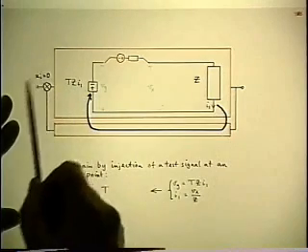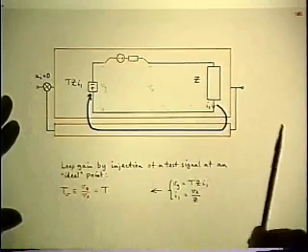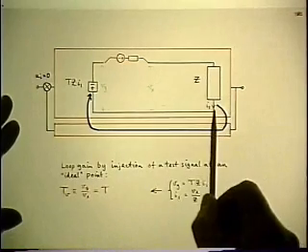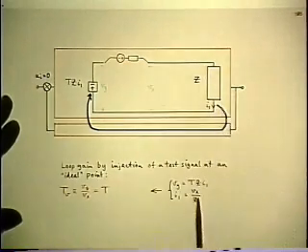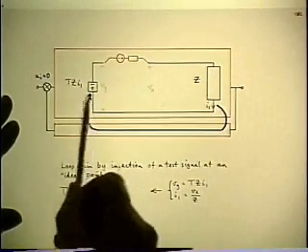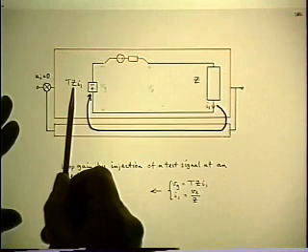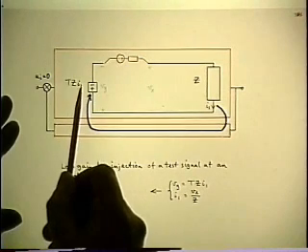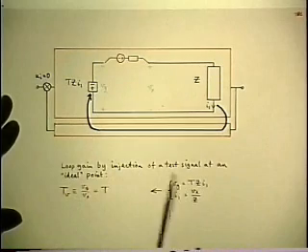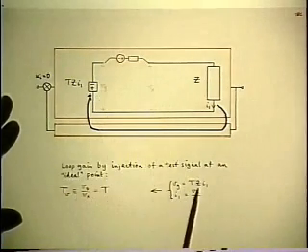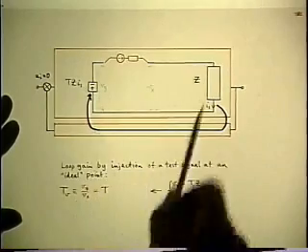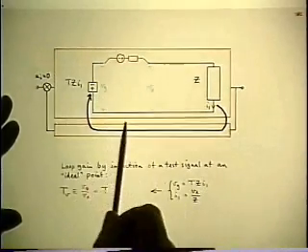Remember, the Ui is 0 at all times when we're working on the loop gain. So the relationship is I1 is equal to Vx over Z. I1 activates this generator, and I'm going to label the generator T times Z times I1, because that voltage is Vy. Therefore, if I divide Vy by Vx, the answer is T. And that's the correct answer because this is the ideal injection point.